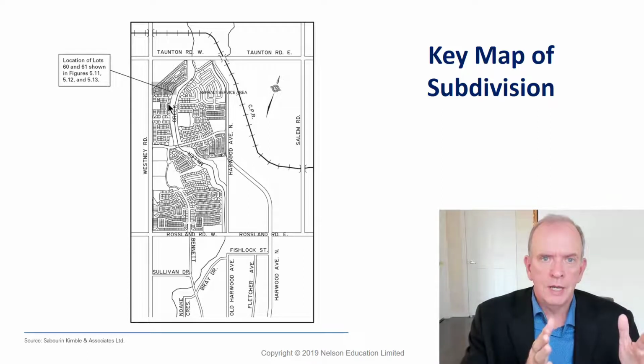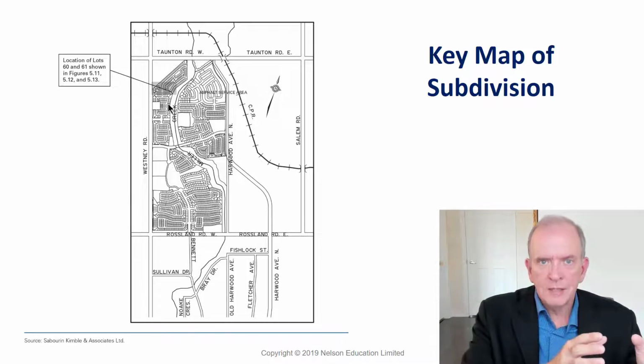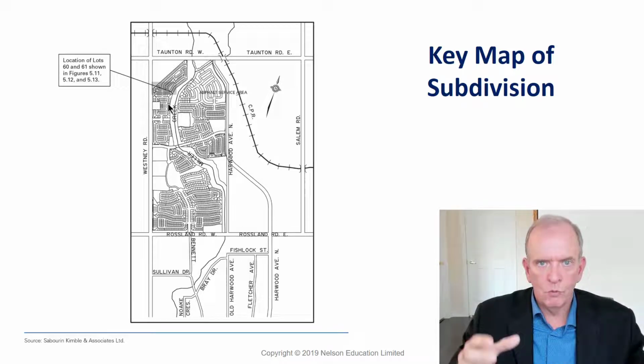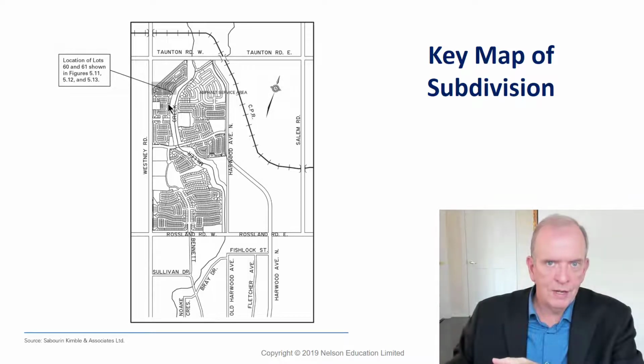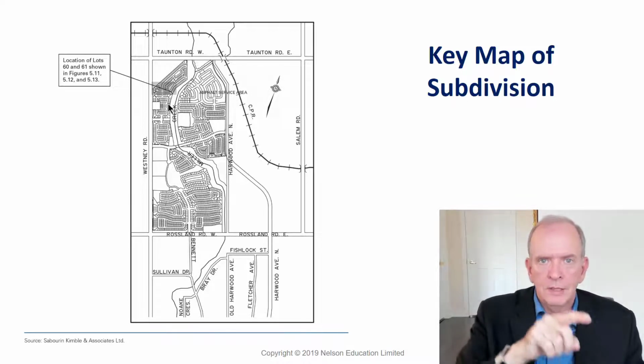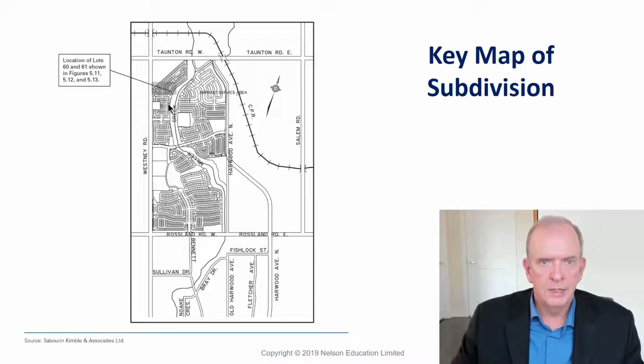What you do is you design it so that you've got houses being built, and then the resources, say the excavation crews, they might be doing excavating 7 houses in 1 week. Then the next week they go and excavate another 7, and they excavate another 7 after that. So it's sort of this linear scheduling or line of balance scheduling that takes place.